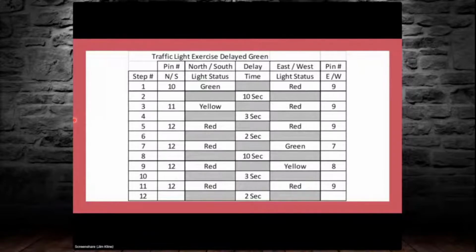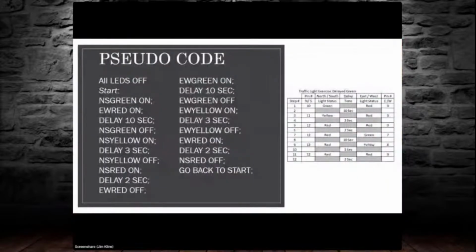However, you could install an interfacing circuit, such as a small transfer relay, that will then use the power handling ability of its mechanical switch to activate the lamp directly from a separate power supply from the Arduino.